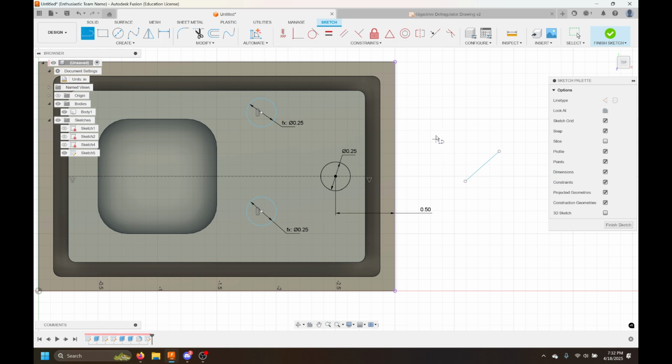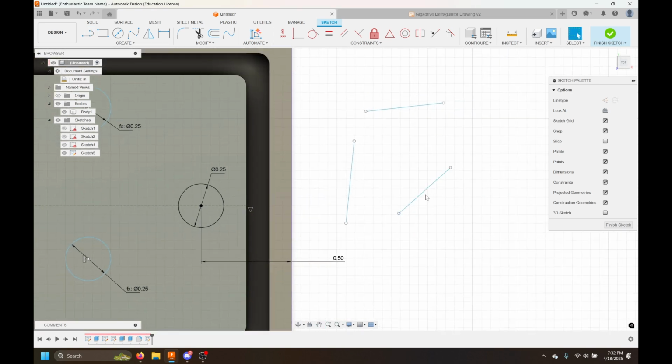I'm going to go into the horizontal vertical tool a little more here. This one is kind of close to 45, but it's closer to being horizontal. So if I do horizontal vertical on it, it'll snap it that way. And then same with these two. That just sets stuff between that direction, and you can do it between points as well. So horizontal, vertical, like that.